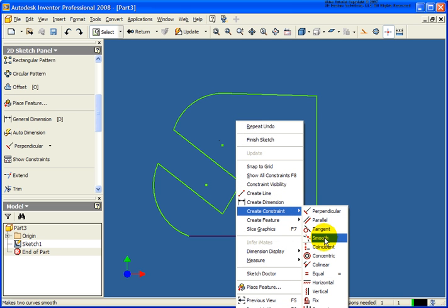And that's going to be smooth. What smooth is going to allow us to do is go back and select a spline and either another spline or an arc segment or another line, and it will be a constant smoothness in between the given segments here. We'll talk about that later in another lesson. The next one is a coincident constraint, and a coincident constraint is going to be that two points touch.